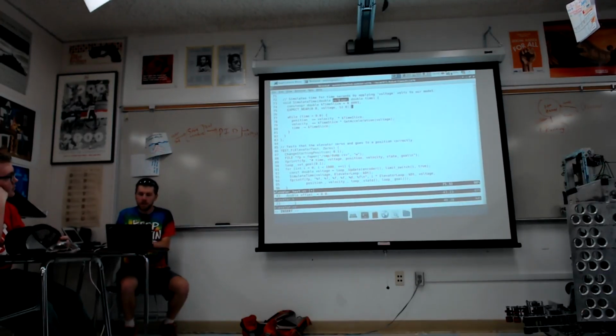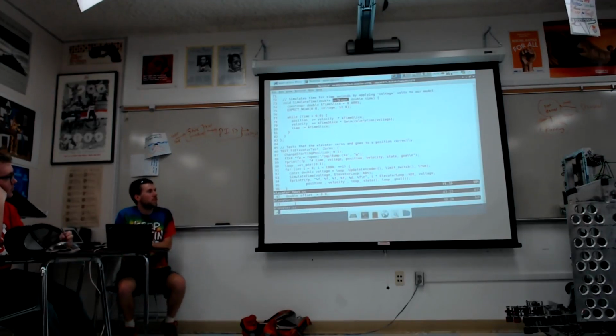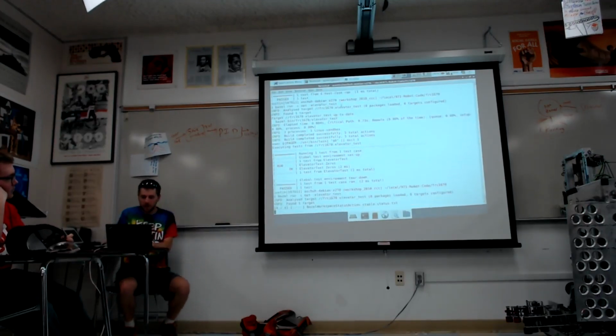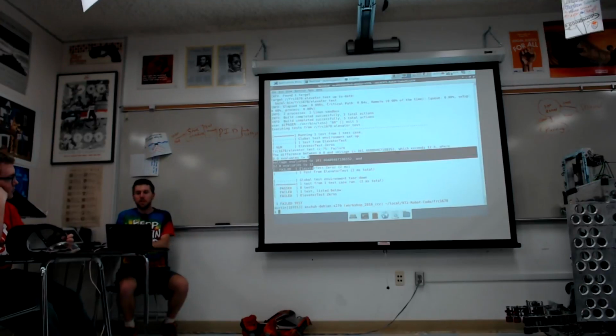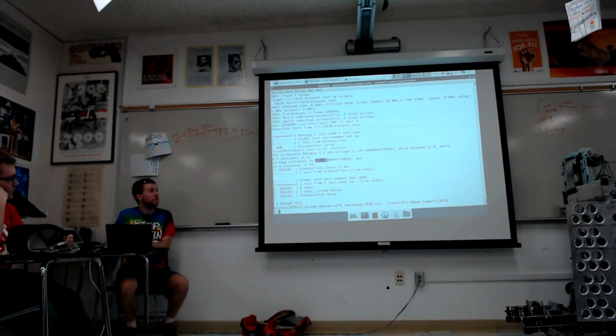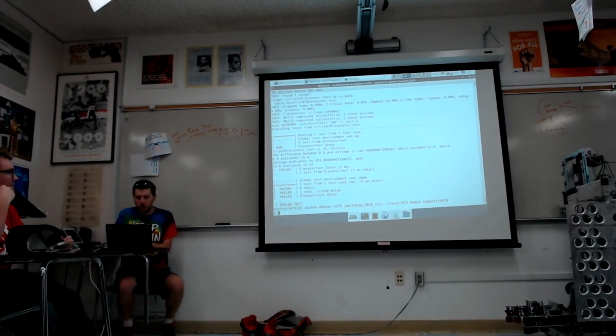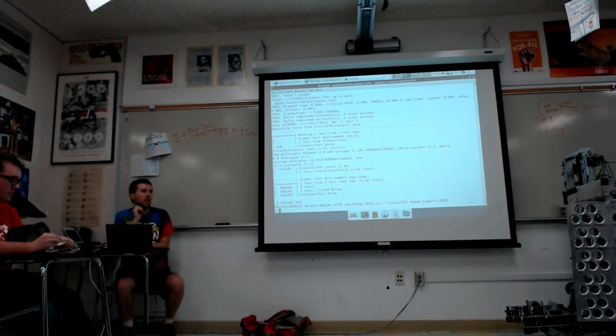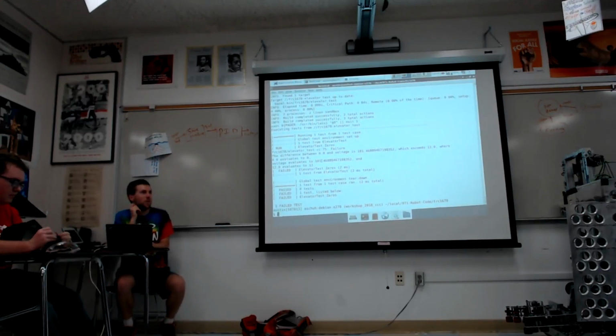I'm going to be a little cute because I don't like typing. If it's within 12 volts of 0, I'll call it a success. Okay, so let's see if our test fails. Oh, good, test fails. We asked for 101 volts. Not acceptable. So now we should go figure out why our software is asking for 101 volts.